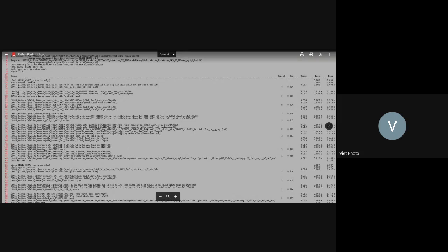If you subtract the clock pin arrival here, 415, right? You minus 1366 minus 415, and you have 951. Sorry, 9, 5, so 951 picosecond, right? That's the data delay.